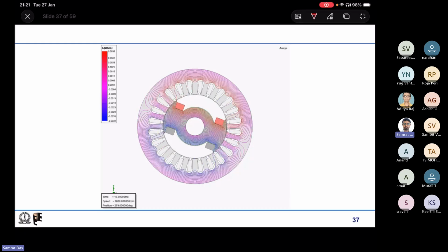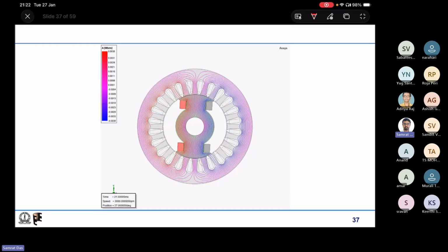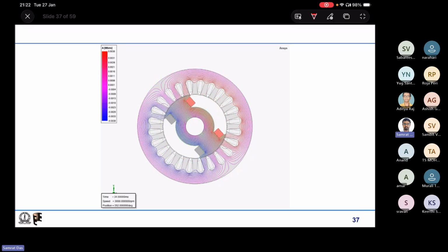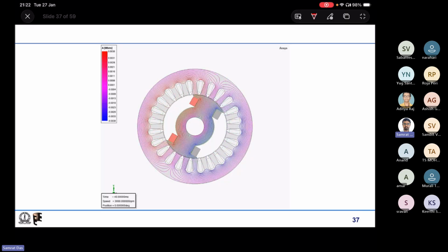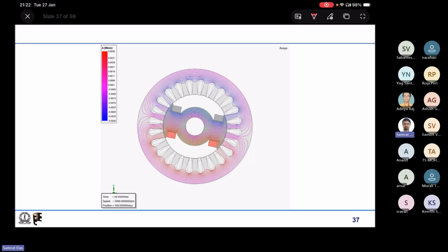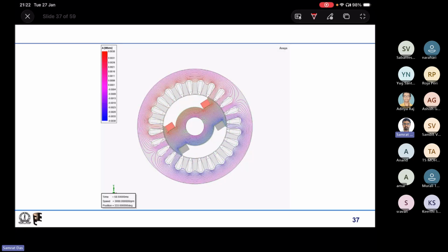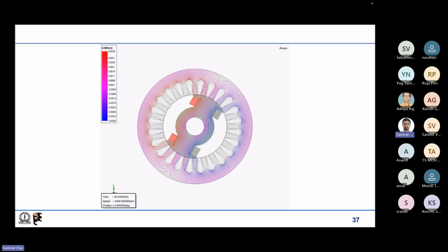So you can see the rotor rotates, the current into the winding of the rotor remains the same. It is a DC current that is passed through that, and with the rotor the magnetic field also tends to rotate in space with the same speed. Because we are looking from a stationary reference frame, because we ourselves are stationary, or how the stator looks at it. So probably I'll stop at multiple instances and help you see that.